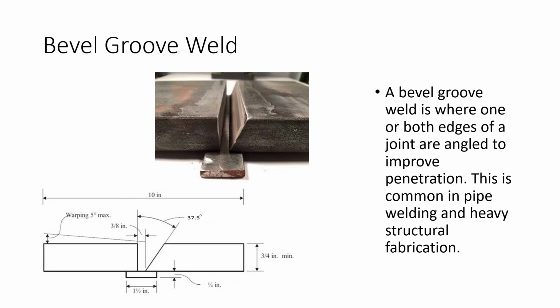This is a bevel groove weld. When we bevel one side to improve the penetration, you're going to see this in pipe and heavy industrial structural fabrication type applications.